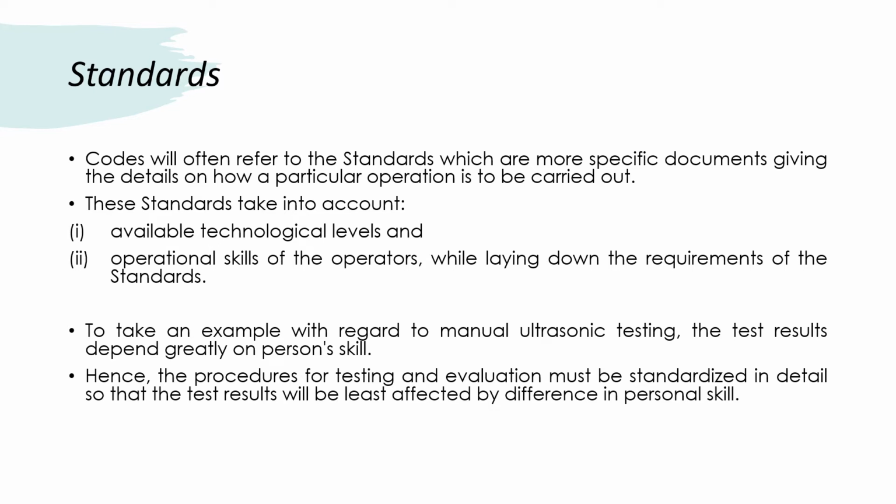To take an example with regard to manual ultrasonic testing, the test results depend greatly on the person's skill. Hence, the procedures for testing and the evaluation must be standardized in detail so that the test result will be least affected by difference in personal skills.